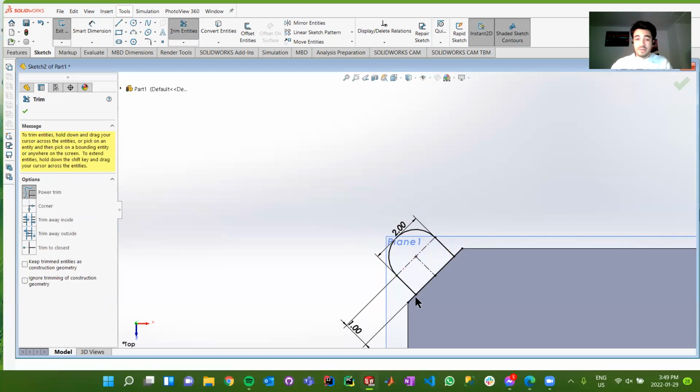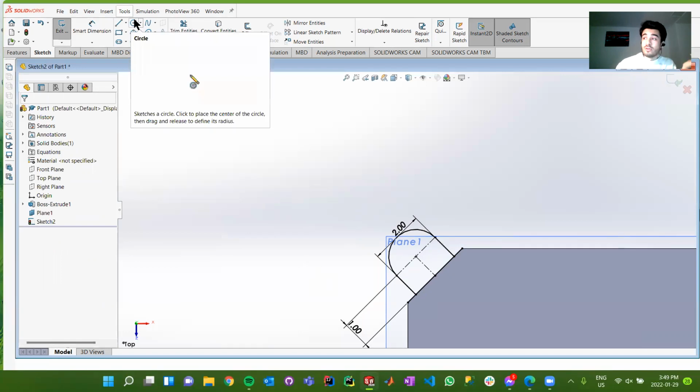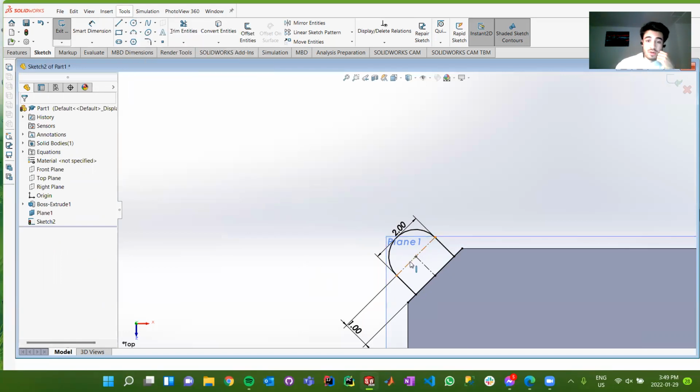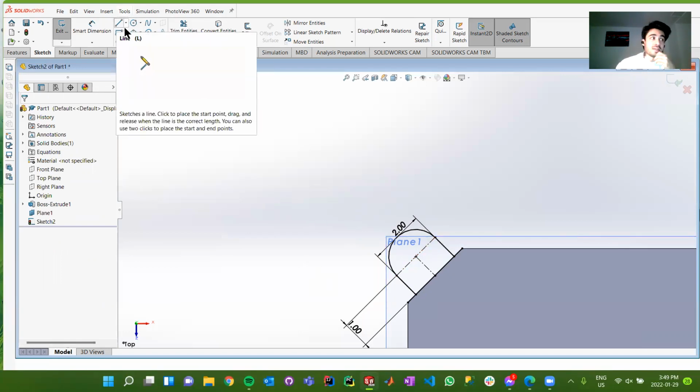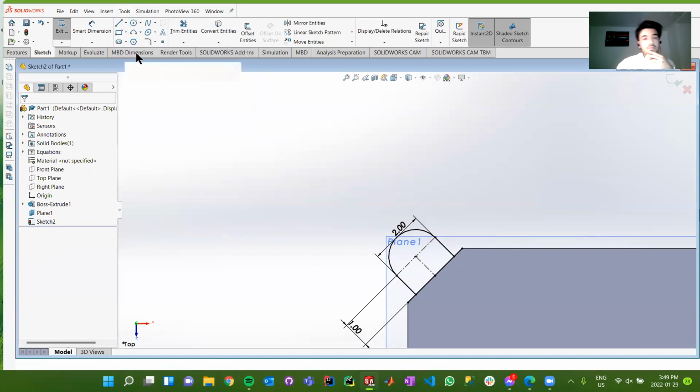And now you can see it is perfectly tangent with the lines that we created because we have this midpoint and this center line established in the first place. You could also put in tangency relations as well. It just won't give you the same effect that I implemented here. And from there, we also need a hole to actually go through. So I think what I used for my CAD was a 5/8 bolt. Let me see, 5/8, yeah, exactly. About 0.625 inches to be exact.